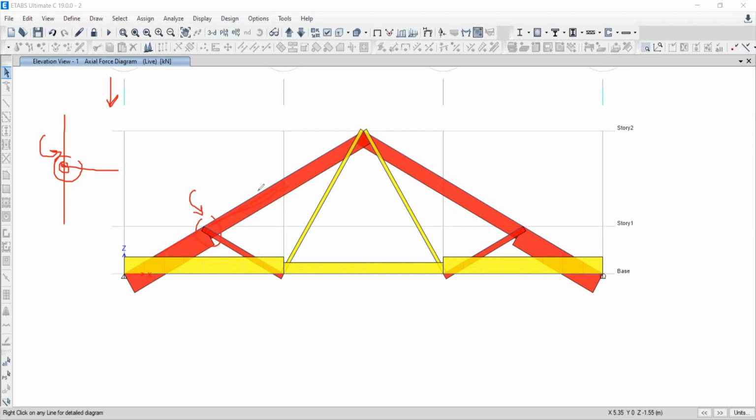Okay, that's why the ETABS software shows the lesser result and your manual calculation shows a little bit more. That is right. In the manual approach, we are considering this joint as a pinned connection. Pin connection means it will not carry movement. The load you applied becomes axial and is transferred. You must have calculated this, where an angle comes with sine, and with that we transferred the load. Do you remember or not? Yes sir, remember. So whatever the total load you apply, that total load is transferred to all the elements.